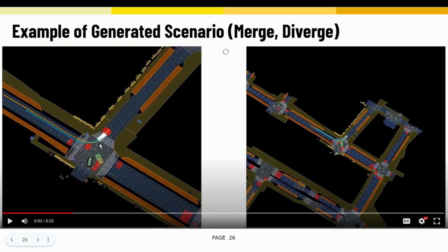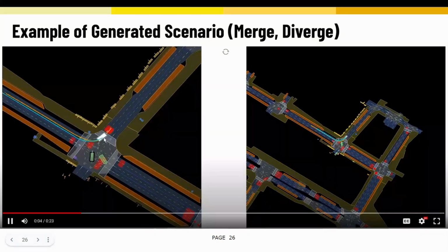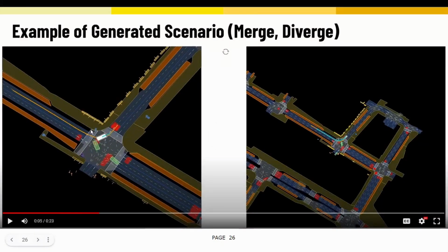The person in this vehicle is still reacting, he's still surprised, he's still scared, he's still got to put his foot on the actual brake. What's the reaction time? We've chosen a reaction time of 1.5 seconds. Literature has shown that this is quite common for people who are surprised by vehicles disappearing. So, we finally noticed the vehicle, but it is far too late to actually do anything about it.